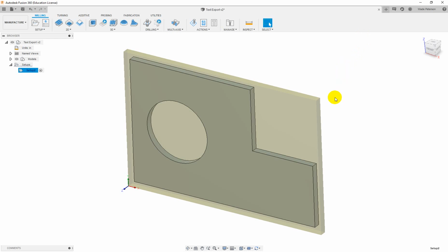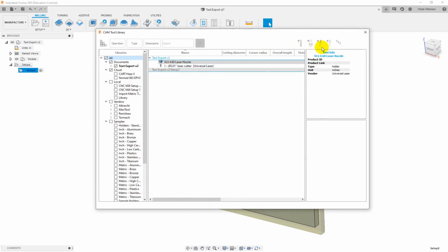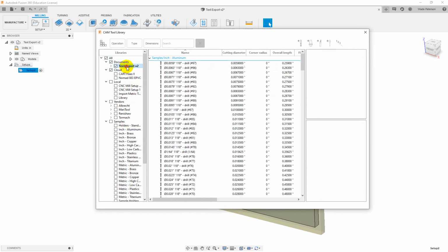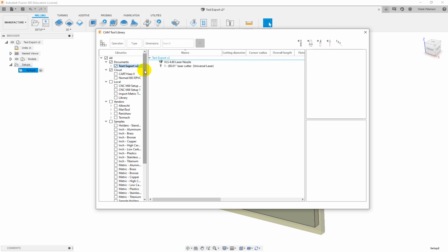So that functionality can be used for milling cutters, lathe cutters, any of the cutters that are in the tool library here. Anything that's listed here, any of these different types of cutters you see in the example files, can be copied over. This is just a convenient way to define your group-specific tools and share them amongst multiple individuals.